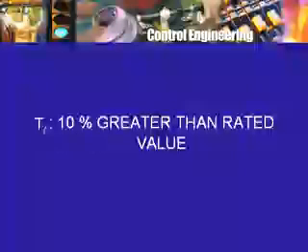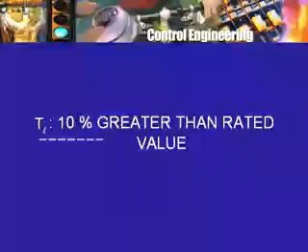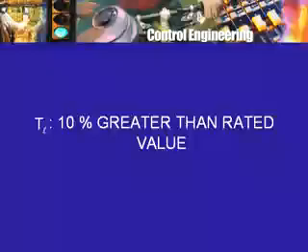So one may say rated torque plus maybe 10% in excess, or maybe one wants to be a little more not conservative but a little more pessimistic, so we will provide for 20% excess. In fact, we can then advertise that, well, our drive will provide for up to even 20% excess power. So 30 Newton meters normally, but it could be increased by 10% or by 20%.